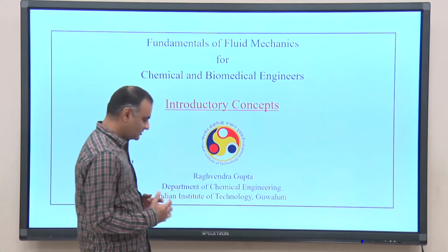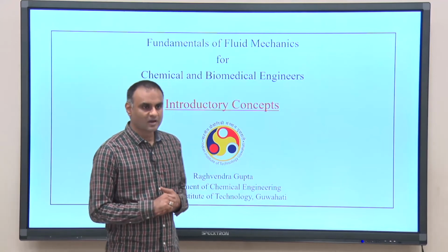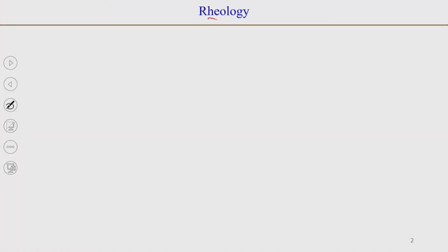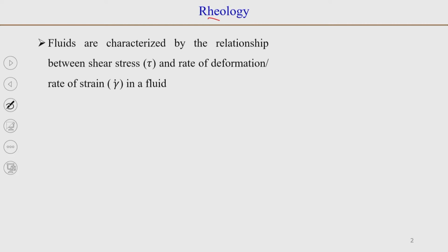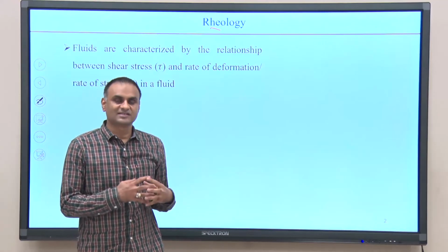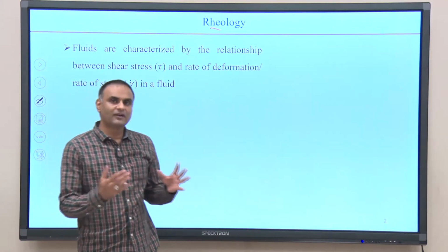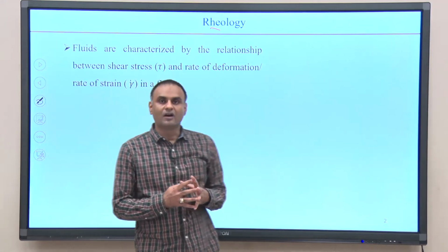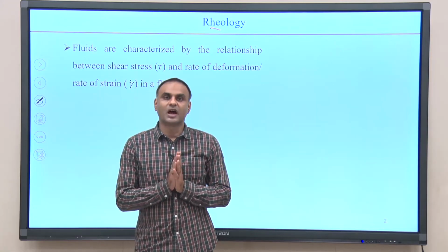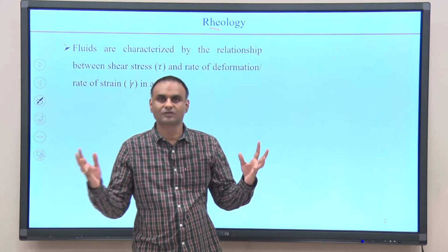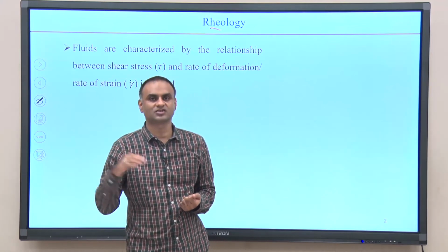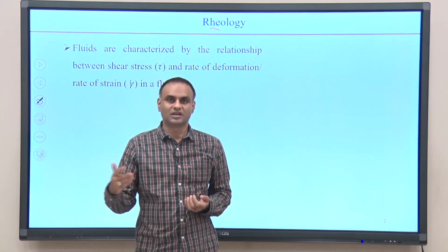Today we are going to talk about some further introductory concepts, and first we will talk about viscosity. There is this name rheology, which is basically the study of the relationship between stress and rate of strain. When we defined a fluid, we said a fluid is defined as a material which undergoes deformation continuously when it is under a shear stress. So, when we apply a shear stress on a fluid, it deforms continuously.